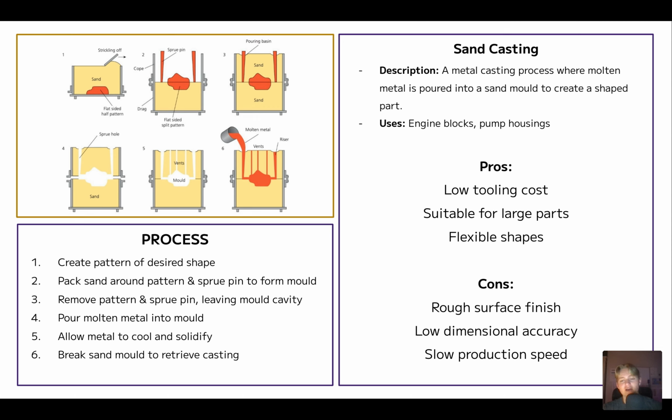And also, there's a low dimensional accuracy because the sand can move and not exactly form to the shape of the blank, so it's not entirely accurate. And it can be quite slow because we're having to recreate the mold every single time, since we are essentially destroying the mold to remove the part.